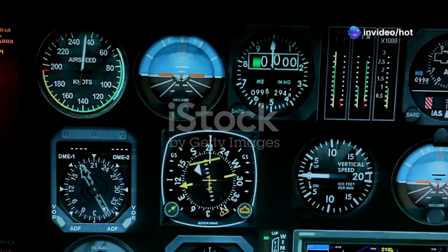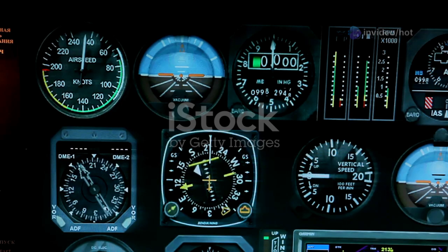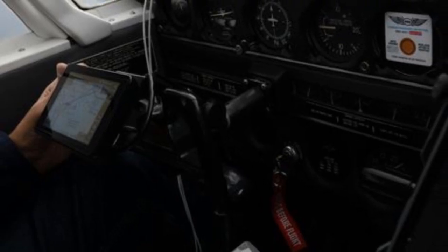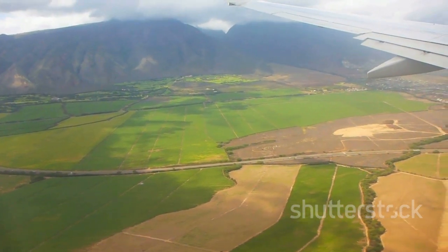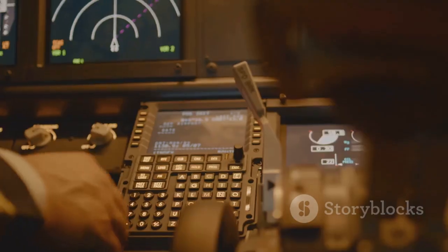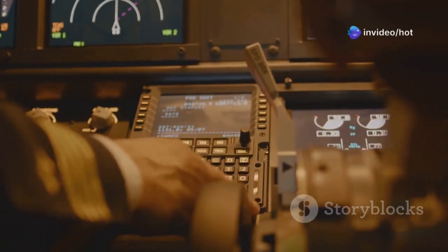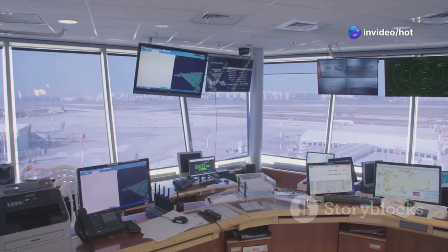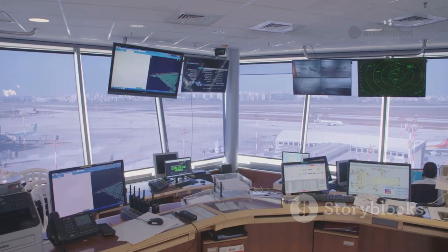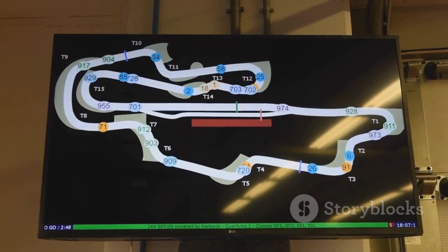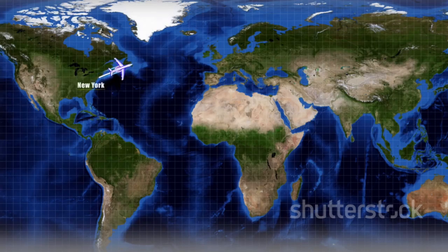One of the most common systems is the semicircular rule. This rule dictates appropriate flight levels. It is based on the aircraft's magnetic track. The magnetic track is the actual path over the ground, not necessarily the aircraft's magnetic heading. Wind can cause a difference between heading and track. The rule divides flight paths into two main categories: eastbound tracks and westbound tracks. This simple division helps organize traffic flow.